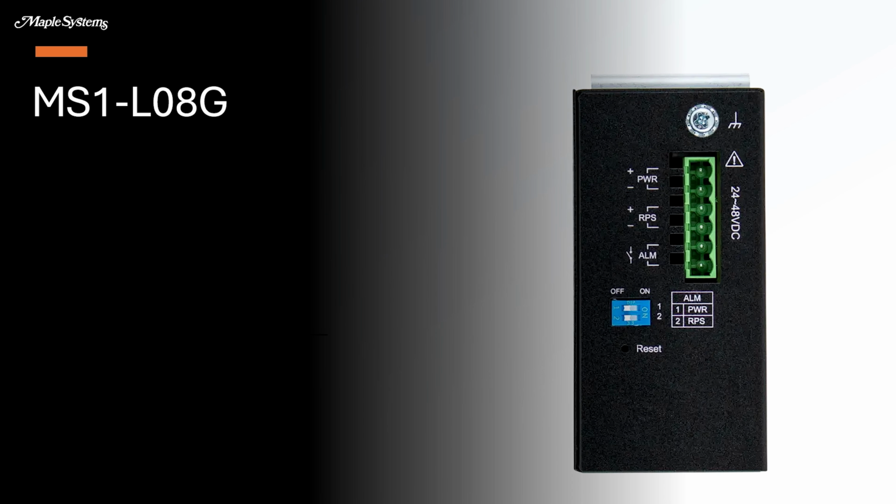Same thing for the MS1 L08G. It offers the same hardware alarm functionality. It has an alarm dip switch located here. So by turning on the power and redundant power system, PWR and RPS dip switches, users ensure that any power irregularities such as voltage drops or redundant supply failures are detected immediately. This configuration adds a layer of protection for critical systems when uninterrupted operation is essential.